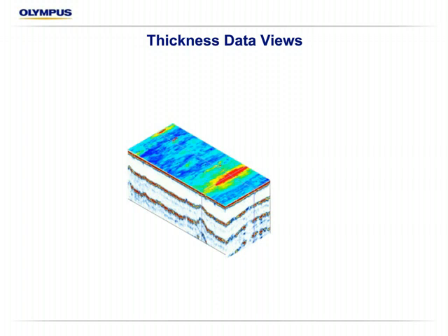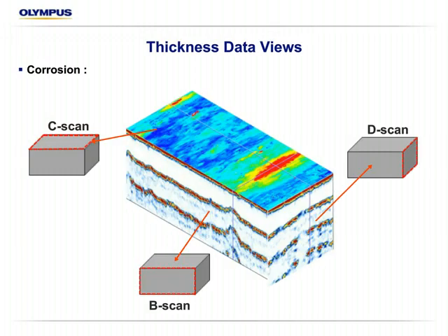Just another assessment of it. So again, the top view, the C-scan, is usually the plan view that we're going to look at to assess things. If we thought this red area, based on our criteria and the setup, was critical, we could click on it and view the data across those two slices where those blue cursors are lying in each axis, so we get a perspective from the entire volume of the vessel or tank or pipe or whatever we're scanning.